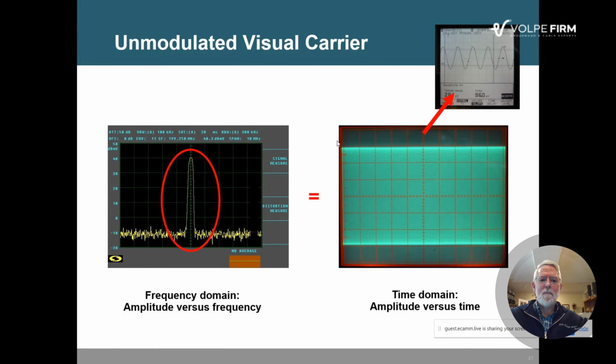And then what you're showing on the right is just a really high frequency representation of a sinusoidal wave that has a frequency of roughly 200 megahertz. So a beautiful slide, Ron. Beautiful. Yeah, you tweak the time per division control on the oscilloscope, and you can see the individual cycles of that sine wave.